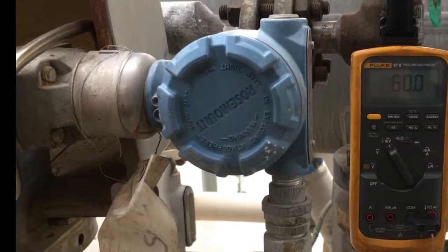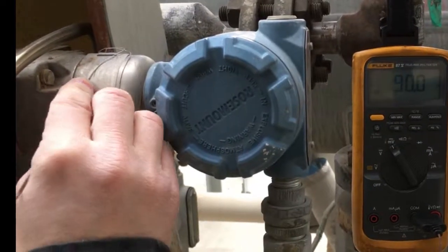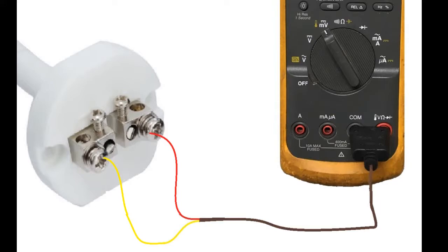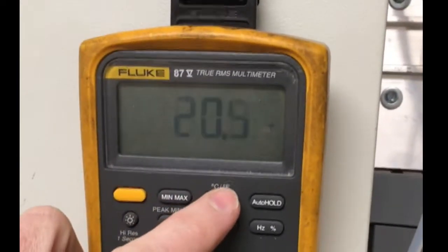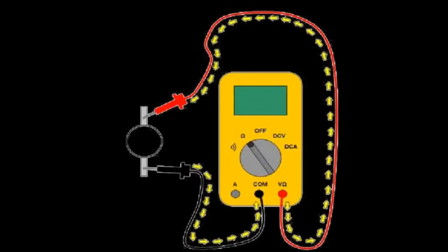The thermocouple can be joined together to take temperature measurements, or the leads can be separated and connected to a Type K element for field verification. Use the range button to toggle the display between Celsius and Fahrenheit. The next dial selection is the resistance measurement mode. The lead connection will remain the same as the previous 3 positions of the dial.